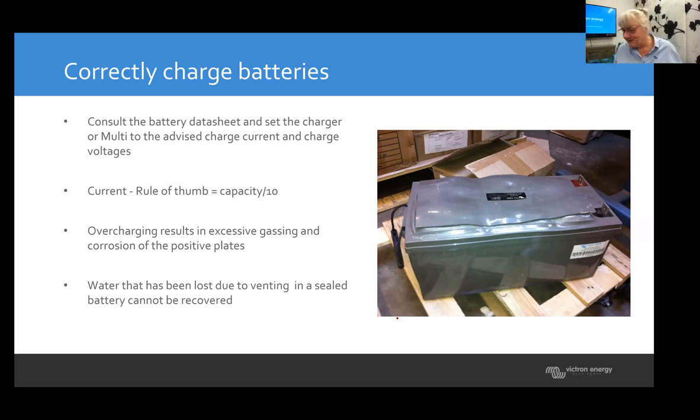So let's actually look at the weight in the data sheet. A 200 amp hour C10 or 220 C20 battery should weigh about 60 odd kilos. And if you have one that only weighs 55, they're sort of glossing things over and it might not be quite there, because the weight is the lead, and that's what the quality of the battery makes.